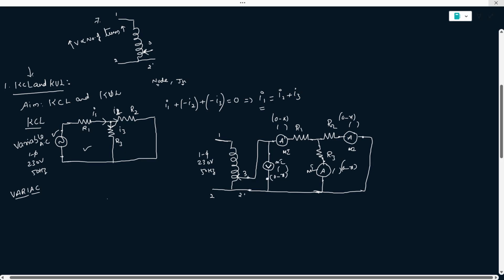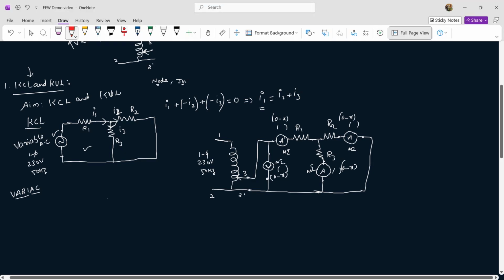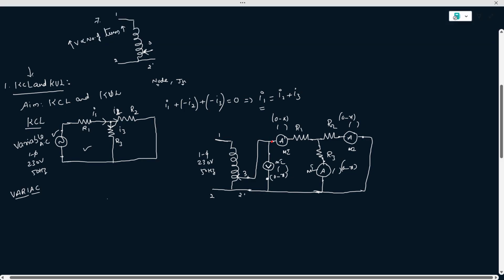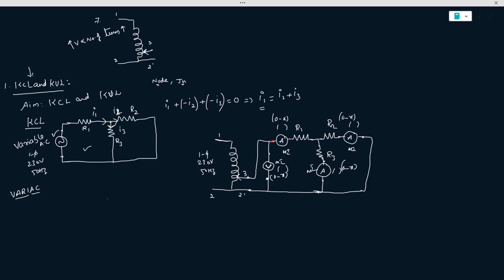So my suggestion is, while connecting the circuit diagram, observe the terminals of each element and connect a wire between the terminals. While connecting these elements, avoid connecting the voltmeters at first. Let us assume the voltmeter is not there, connect all the circuit elements, and finally connect the voltmeter in the circuit.